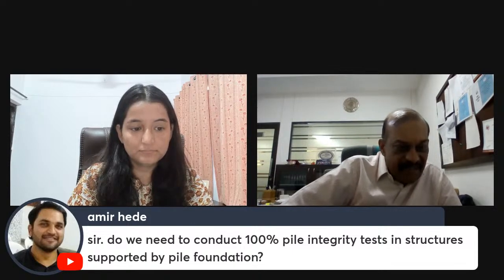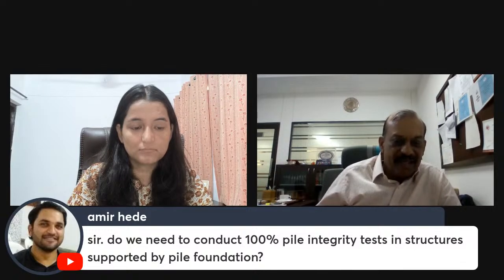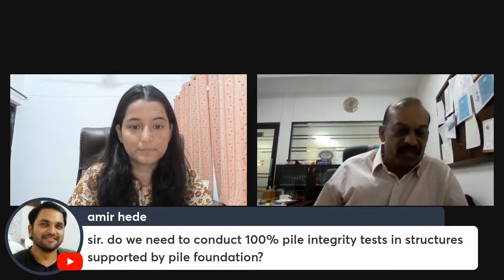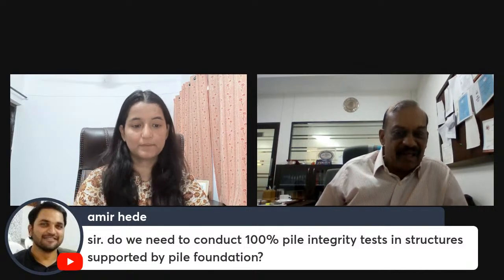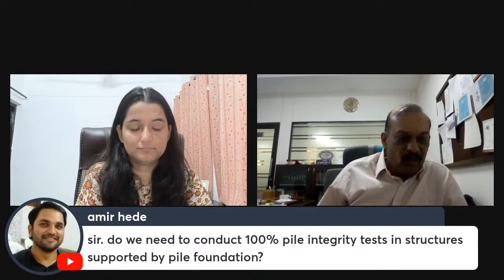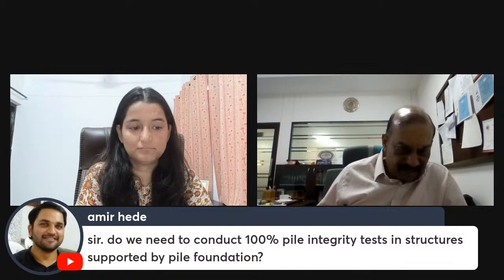It is very important that you conduct low strain pile integrity tests on most of the piles. If you are very confident that all the piles are okay, and whatever piles you tested you find they are good, maybe it is not necessary.